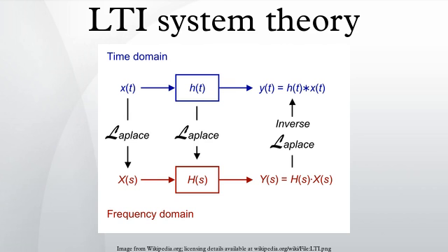Formally, the DT signals studied are almost always uniformly sampled versions of CT signals. If x(t) is a CT signal, then an analog-to-digital converter will transform it to the DT signal x[n]=x(nT), where T is the sampling period. It is very important to limit the range of frequencies in the input signal for faithful representation in the DT signal, since then the sampling theorem guarantees that no information about the CT signal is lost. A DT signal can only contain a frequency range of limited width. Other frequencies are aliased to the same range.